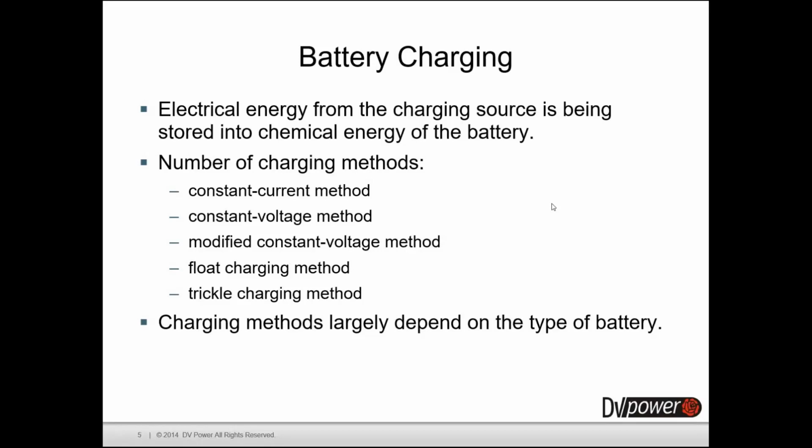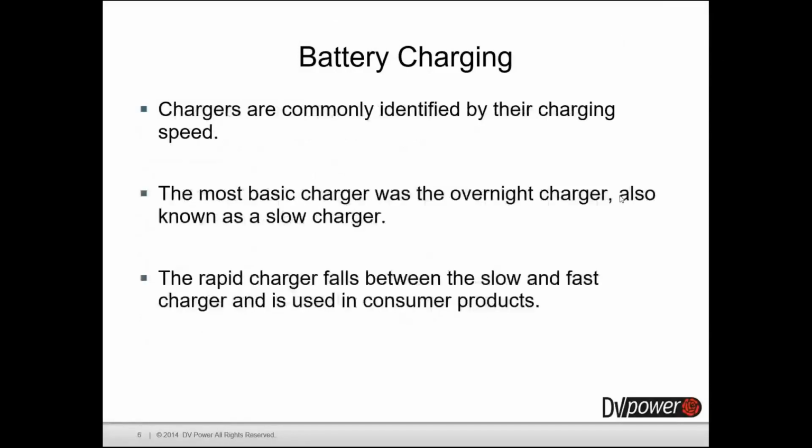We rely on the manufacturer's recommendations. Sometimes manufacturers don't provide that in their usual small brochures, but if you ask them, they will provide you with all the information regarding the charging current, the voltage threshold, etc. You need to ask if it's not available in the battery brochures online.